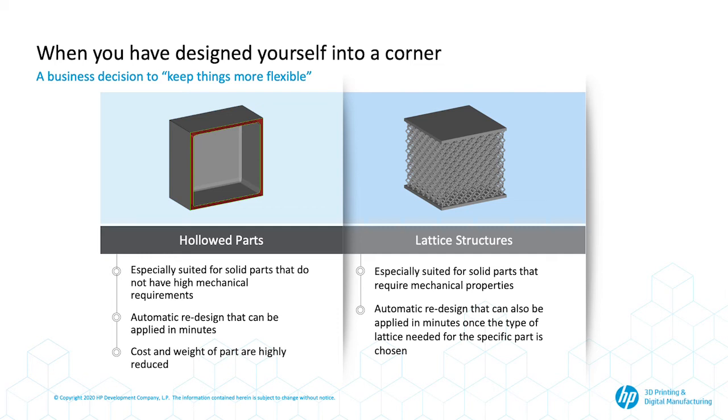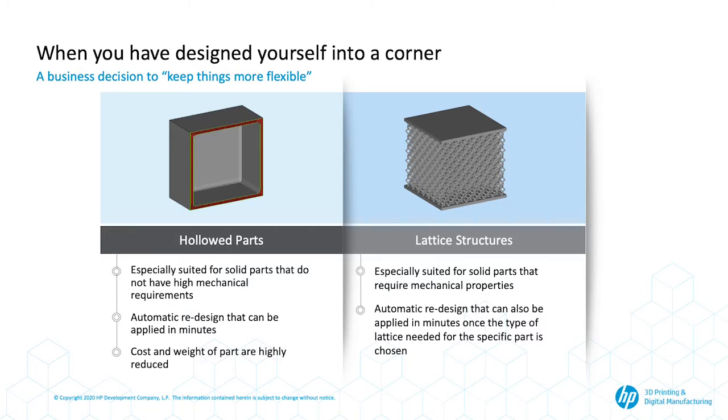For those components, in cases where lightweighting or reduction of material cost might be beneficial, 3D printing gives you tools to play around with the design of that part, like hollowing certain structures to reduce the material, or using lattice structures to keep the same performance and durability of the component while using less material and having more organic designs. That's when you're dealing with a component that has been designed the same way and used the same way for a very long time.